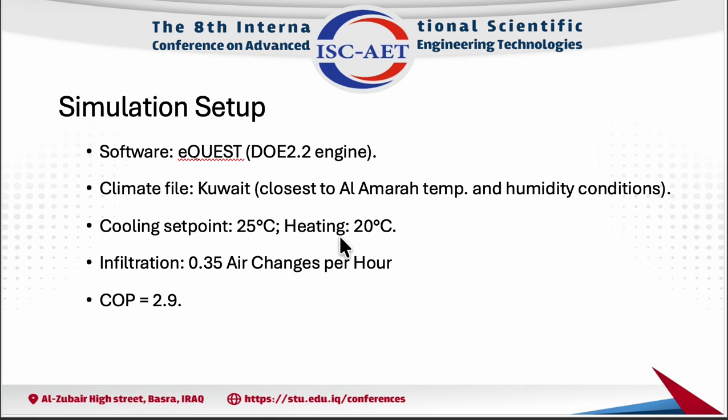And the heating set point was 20 centigrade. The infiltration rate was 0.35 air change per hour. The HVAC system coefficient of performance, which is called COP, is 2.9. This setup ensures consistent, realistic, and comparable results across all wall systems. Now let's move on to the building model.